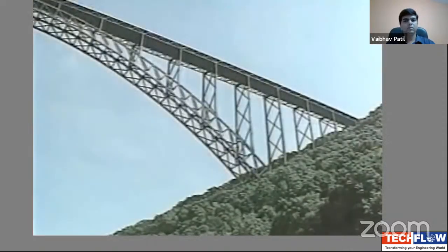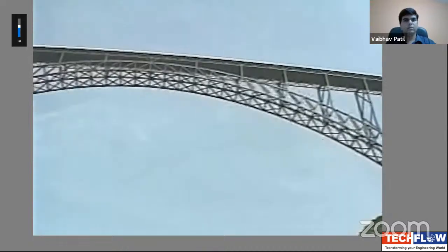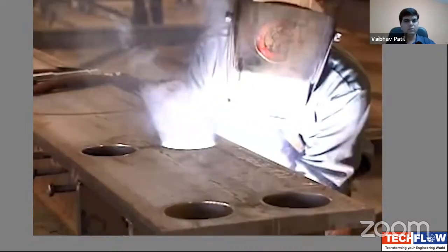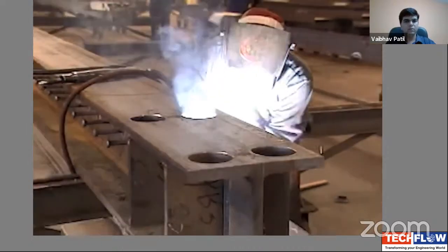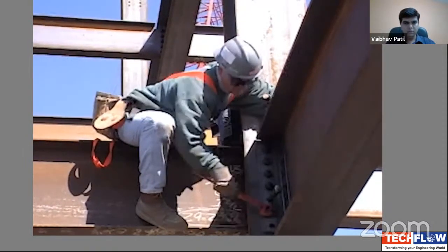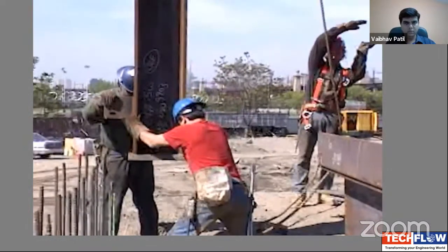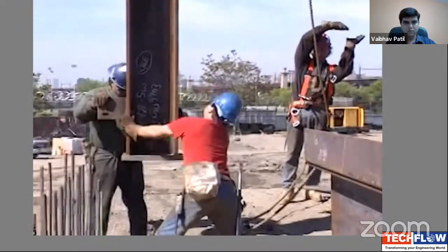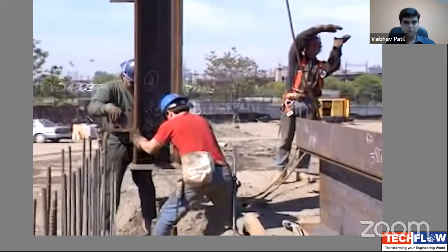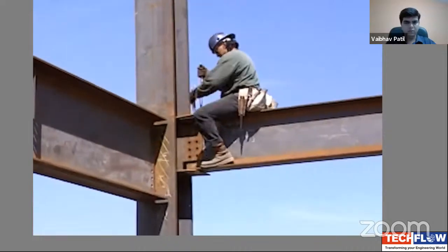After the steel has been produced, every piece of steel in a skyscraper or bridge must be precisely cut, its holes properly placed, its pieces welded in exactly the right location. Every single bolt in the structure must be located and attached at the proper place, and all this must be exact to 1/16th of an inch, so that the steel members will fit together perfectly at the site.